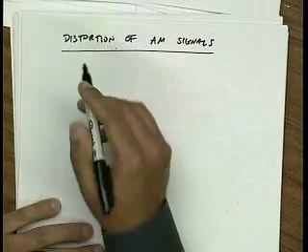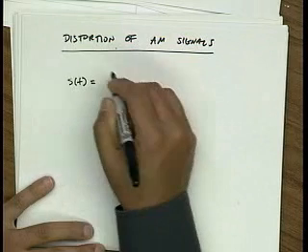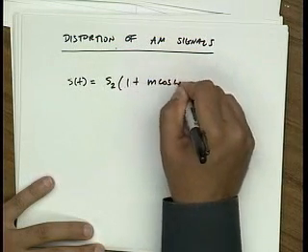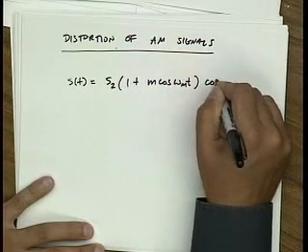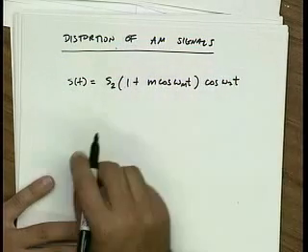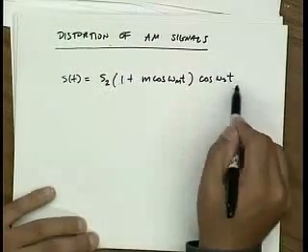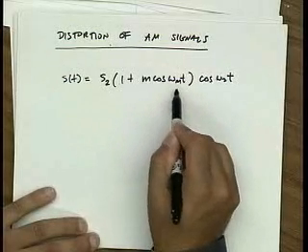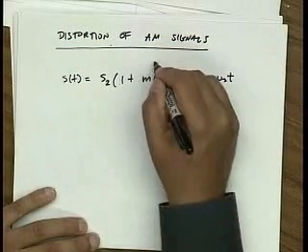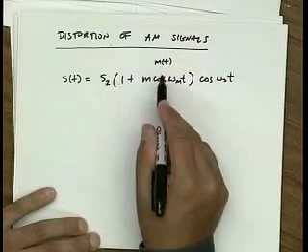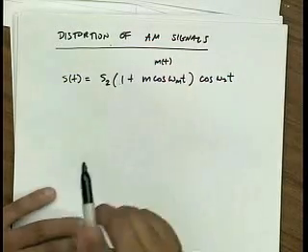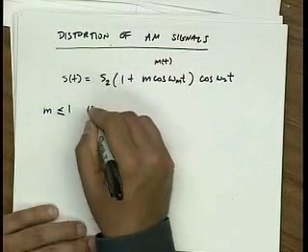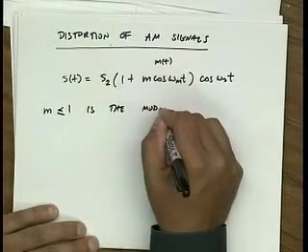Now, with amplitude modulation, we can represent the signal in this generic form. And because the mathematics gets way too ugly, we're going to assume we have a carrier, that's omega 2, and it's being amplitude modulated by one tone, omega m. In general, I should write m of t as the modulating waveform, but here I assume that I just have one tone of modulation. So m, which is less than or equal to 1, is the modulation index.